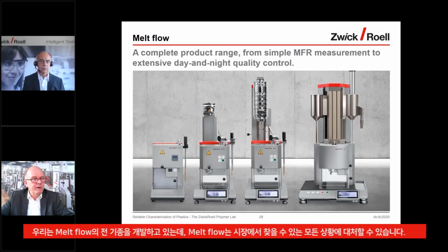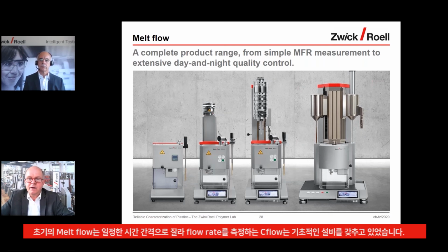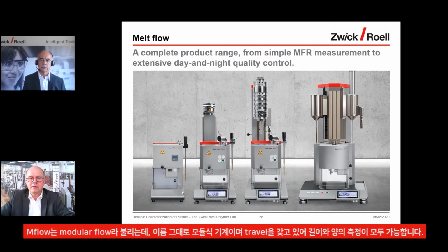Yeah, we have developed a complete range of melt flow plastometers, and it covers, let's say, all different situations that we find in the market. It starts from a very basic instrument. We call it the C-Flow, the Compact Flow, which is just able to measure melt flow rate by cutting in constant time intervals and by weighing the extrudates.